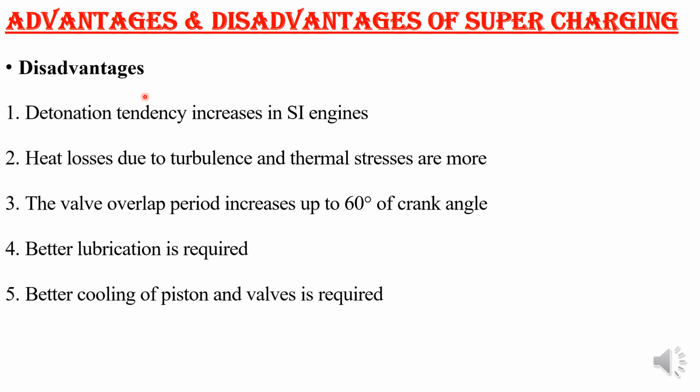Heat production is more, that means most of the material will go into thermal stress, and heat losses or high temperature it will encounter, and so cooling of the piston and valves is required. So a very good quality of cooling should be required. So the cooling system has to be improved. So that may lead to a disadvantage of your supercharging.